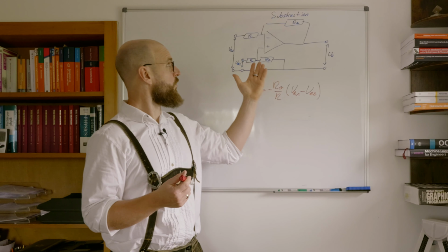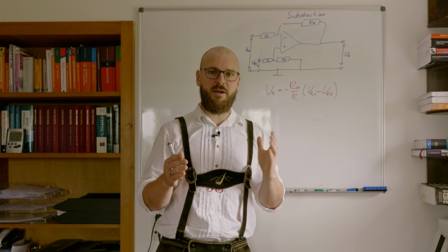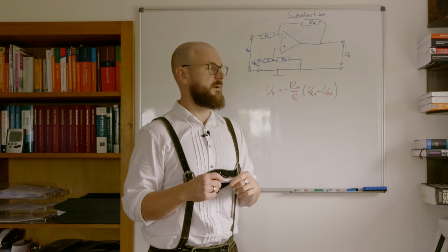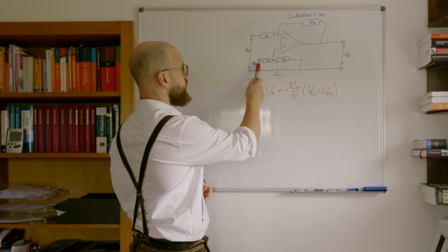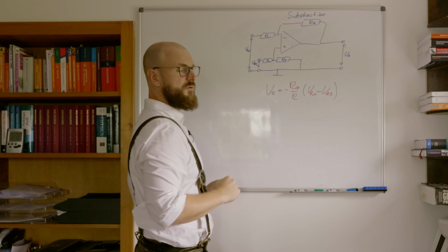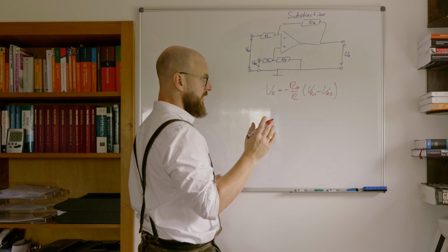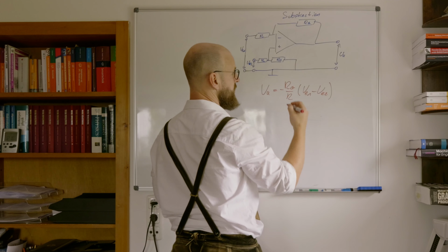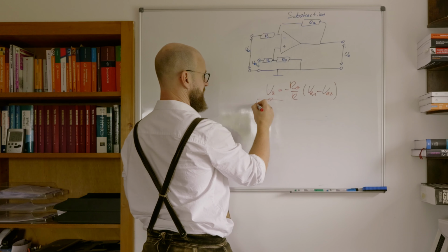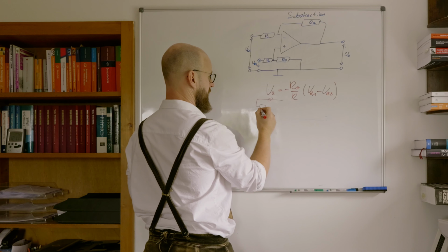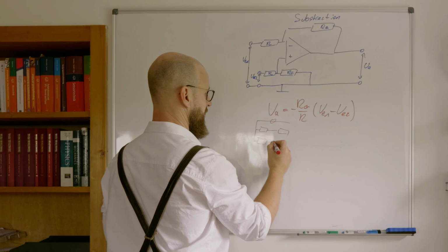And the idea why a subtraction amplification is important is not the subtraction of the voltages itself, but that you are able to take two potentials relative to the earth and subtract them from each other. One simple case you need to use such an electrical circuit are those measurement bridges. Think of those measurement bridges over here. We already did in the chapter for resistors.